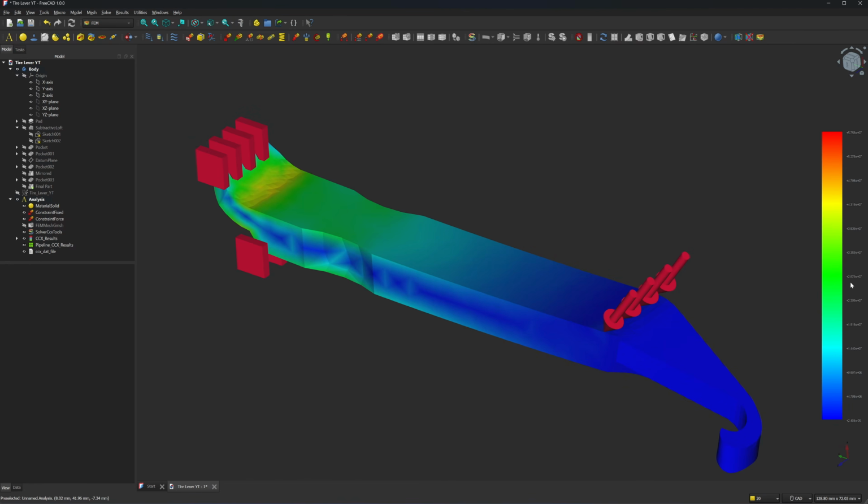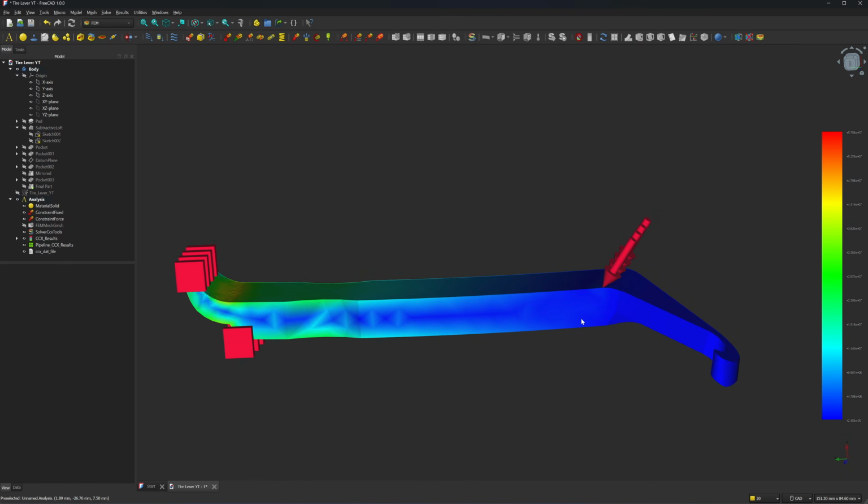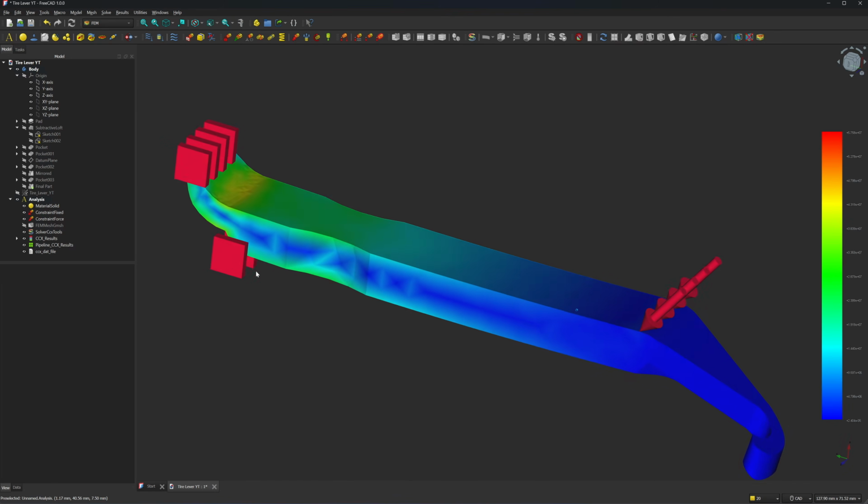That means it's 28 megapascal. So this one is very close to a breaking point. This color, the green color. Anything that is in the green color will break when you apply 6 kilograms of load. So it will start to tear from the surface here.